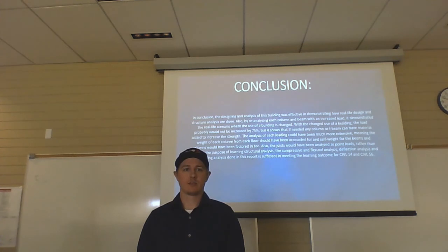The analysis of each loading could have been much more extensive, meaning the weight of each column from each floor should have been accounted for, and self-weight for the beams and columns would have been factored in. Also, the joists would have been analyzed as point loads rather than UDLs. For the purpose of this learning, the structural analysis, compressive and flexural analysis, deflection analysis, and full loading analysis done in this report is sufficient in meeting the learning outcomes of Civil 14 and Civil 56. Thank you.